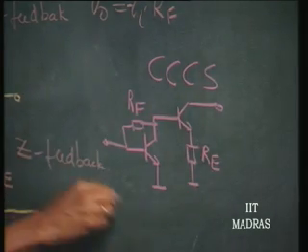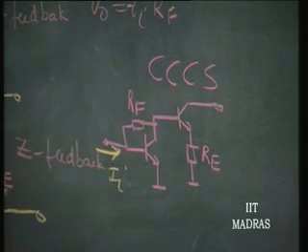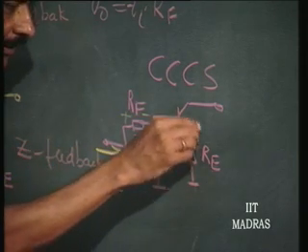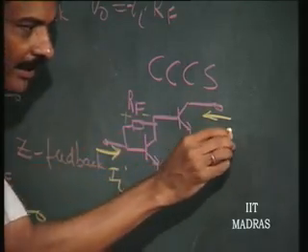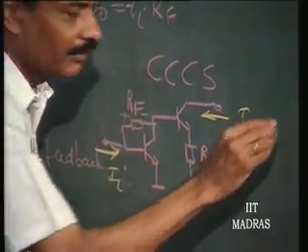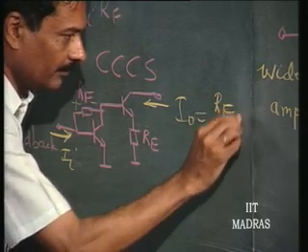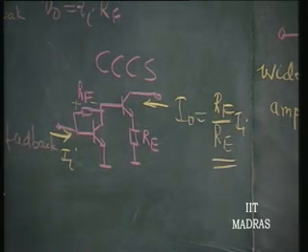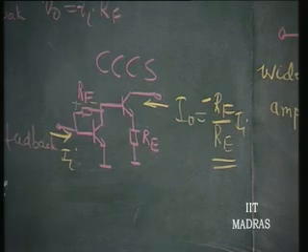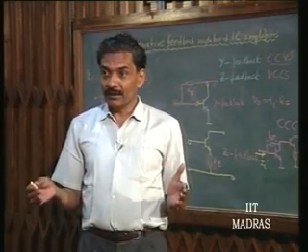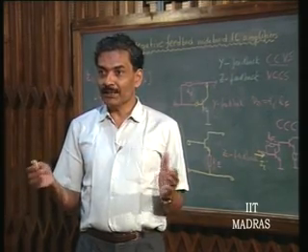So the current gain is, let us see, if this is the input current II, this current will go into this as II into RF, that will be divided by this, meaning current will be going into this stage, and I naught equals RF divided by RE, with the current in the other direction, so it is going to be minus. Is this clear? So this is a wideband current amplifier of gain equal to minus RF over RE.